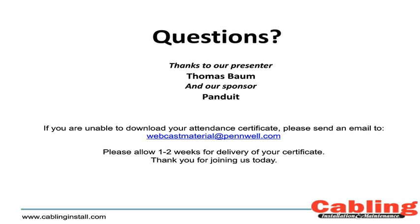Okay. First of all, thank you for the questions. Really appreciate the interest in sending in questions during the presentation. To the question, they're not really more susceptible to microbending. When you look at the minimum bend radius for cabling, it's typically based on 4x the cable diameter. So naturally, with the cords being much smaller in diameter, they allow a much smaller bend radius than the corresponding 24-gauge patch cords. But that does not mean that they're susceptible to microbending.